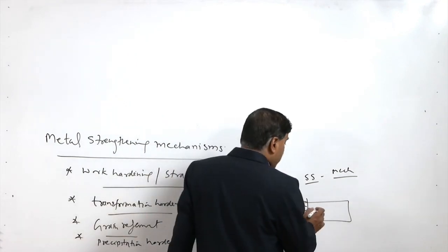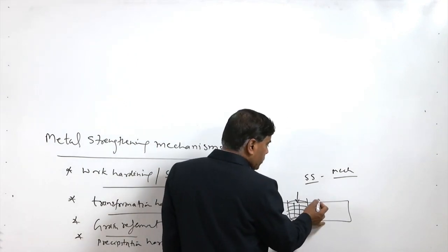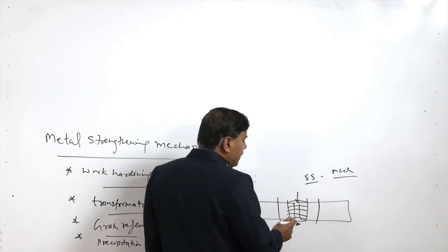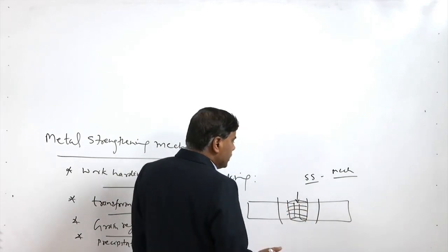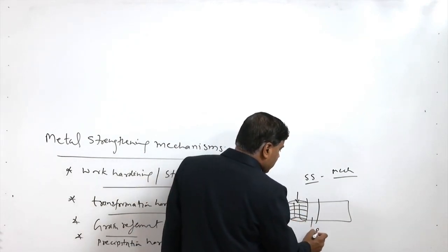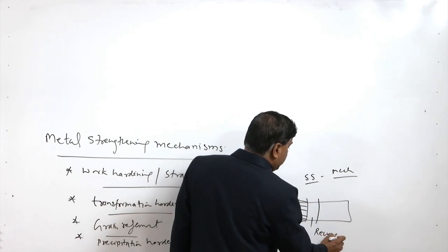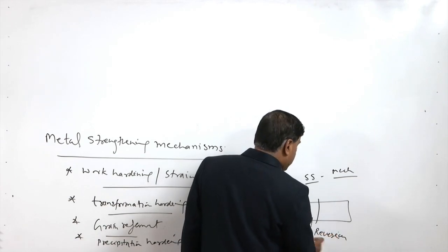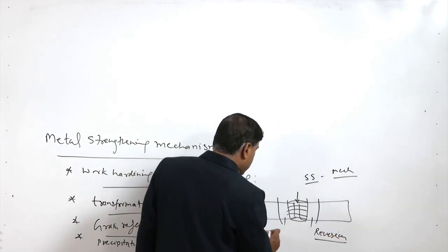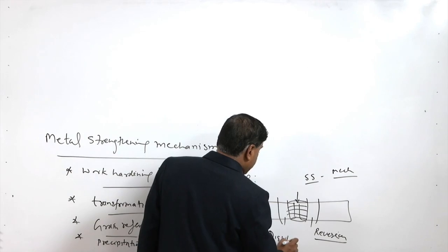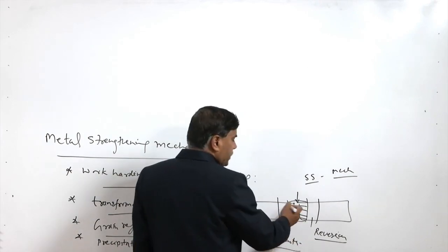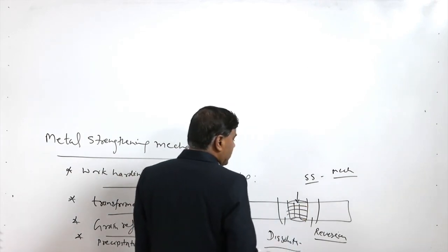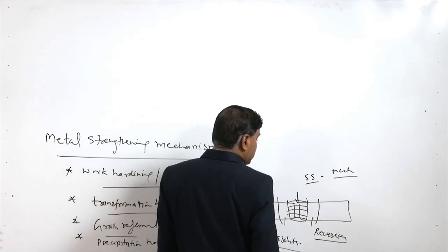On the other hand, what about those locations which have been heated next to the fusion zone? This is the area where partial or complete reversion, or dissolution, of the precipitates will take place.